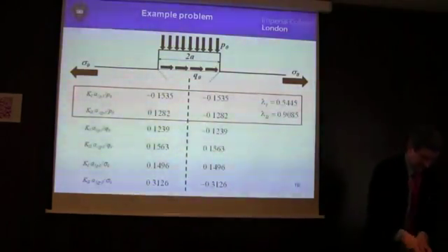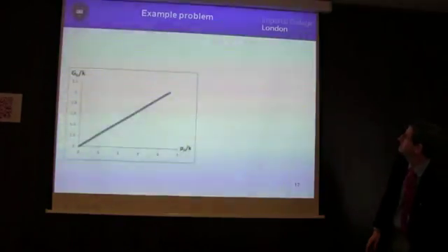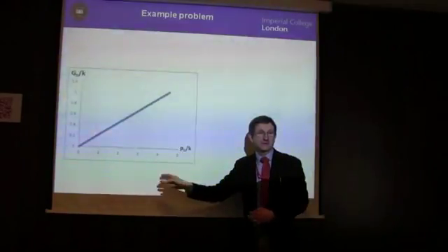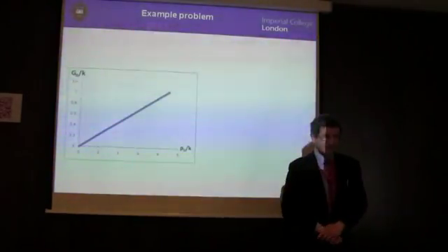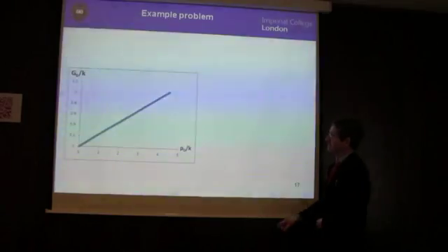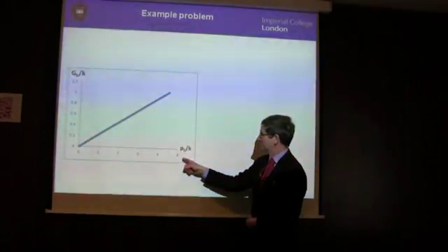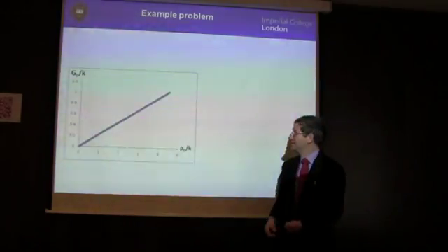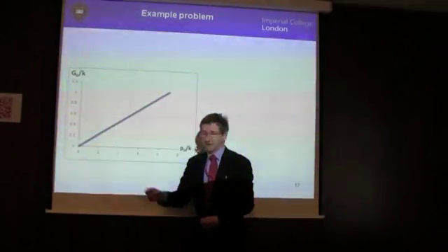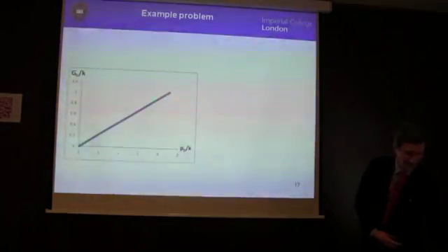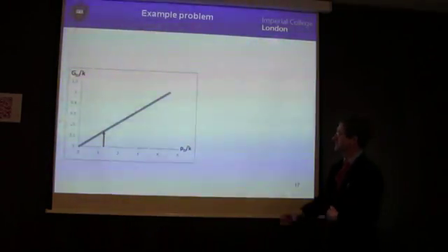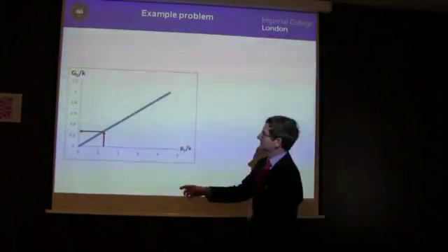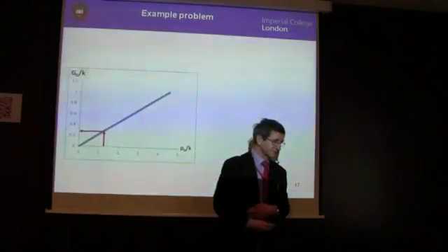From that, you can calculate the G0 in terms of P0. And again, if only I'd thought about this yesterday instead of today, those of you who are on the ball will realise that it would be ridiculous to put this value as high as 5. The thing would have gone completely plastic by then. A more sensible scale here would have been from about 0 to about 2. But anyway, if you know a particular contact pressure, you can calculate the value of G0.